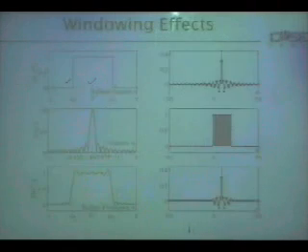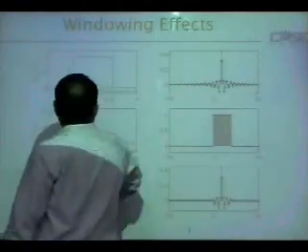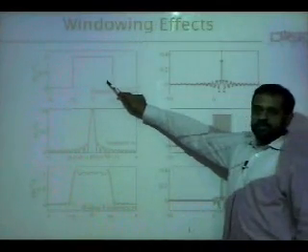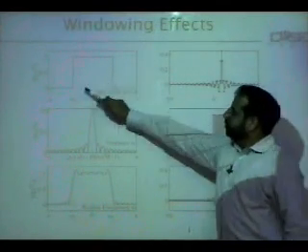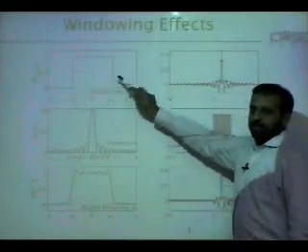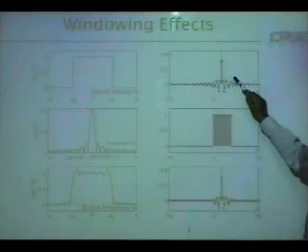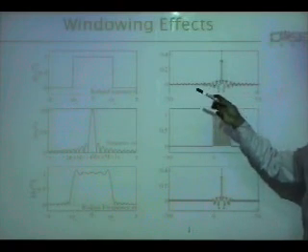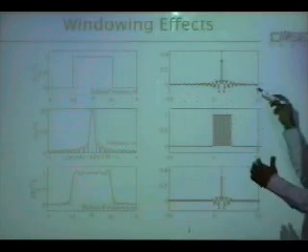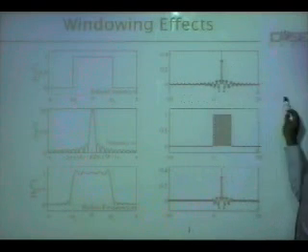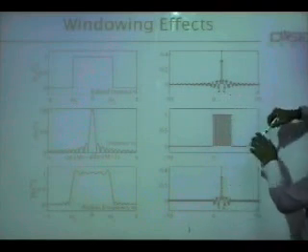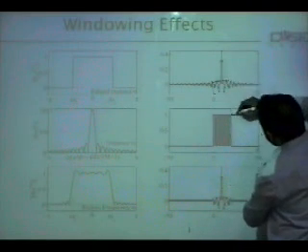So the magnitude, if you plot it as a nice MATLAB slide, this is the ideal filter in the frequency domain. Its inverse Fourier transform is infinite, though you cannot create an infinite signal in MATLAB, so it's just representing something which is infinite, a sinc. Now you want to window it, so it's a shifted sinc. You want to window it from here to here, right?